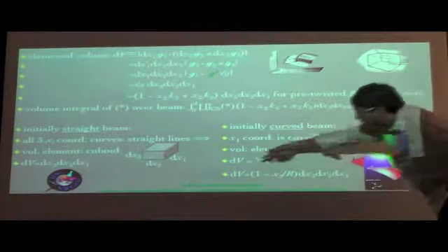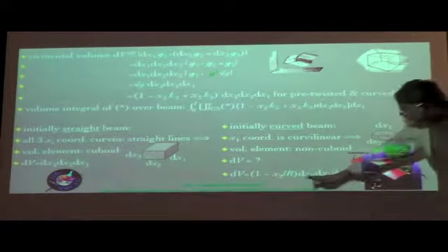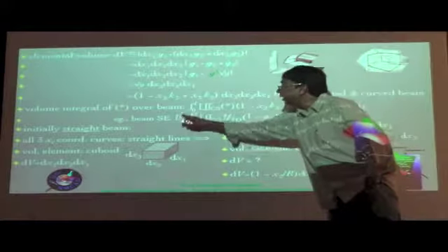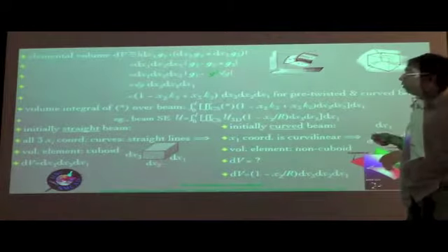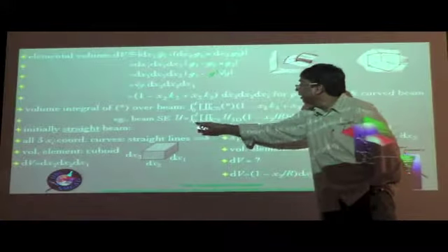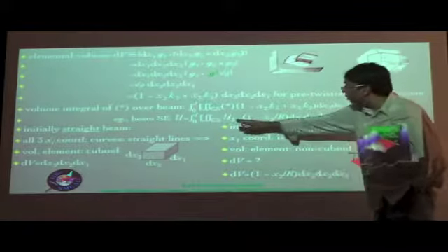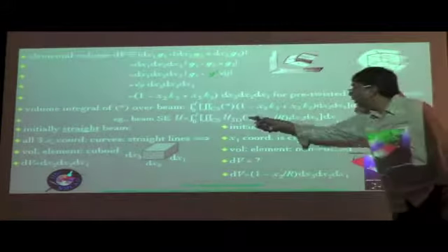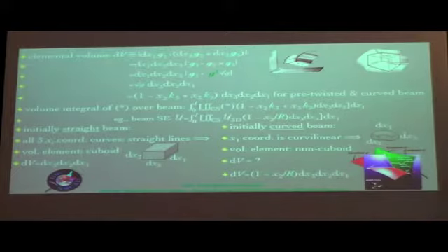So therefore, in our specific example, dV is now 1 minus x2 divided by r multiplied by the three elements dx3, dx2 and dx1. And the strain energy that we have to write eventually, for minimization or determining the stationary points of the functional, is basically the integral from 0 to L, integral over the cross section, of the energy per unit length or energy per unit volume of the material involved in the beam, times 1 minus x2 by r, and then the corresponding elemental lengths.